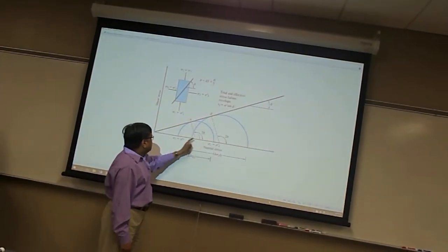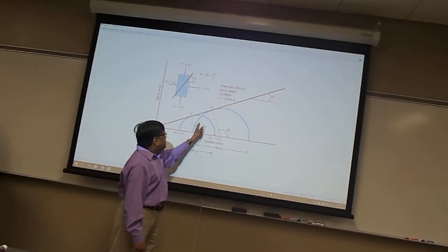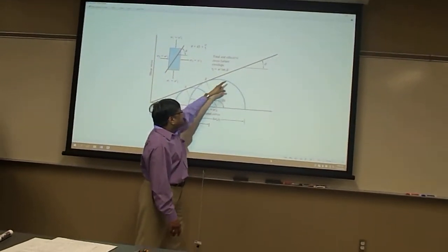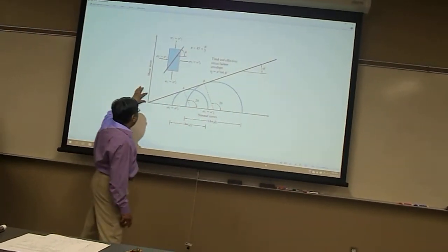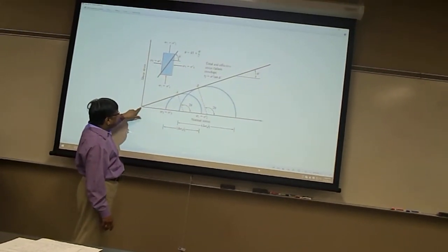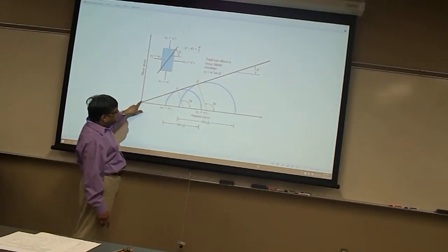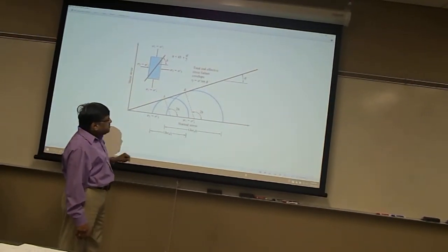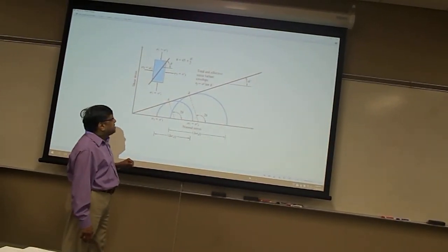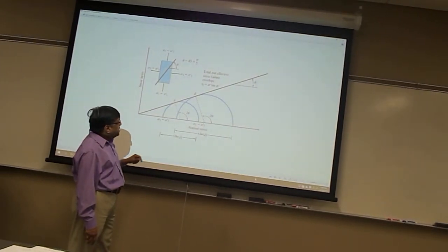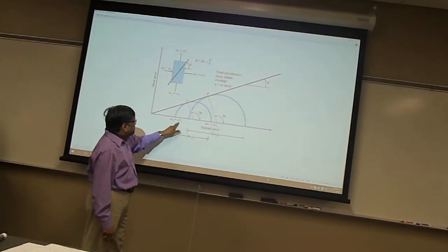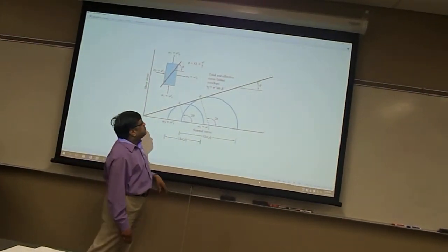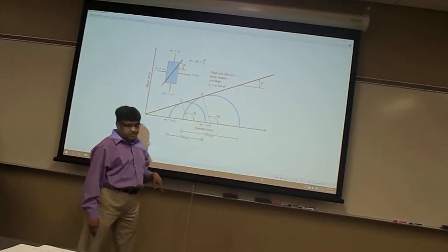The Mohr circle: sigma 3, sigma 1, sigma 3, sigma 1, 2 Mohr circles. We have a common tangent with the slope phi prime. We can also have a y-axis intercept, but in this case the y-axis intercept is 0. C or C prime is 0. This is for the first type of triaxial shear test, consolidated drained shear test. That's why sigma 3 and sigma 3 prime are equal. So we get one set of Mohr circles, not 2 sets of Mohr circles.